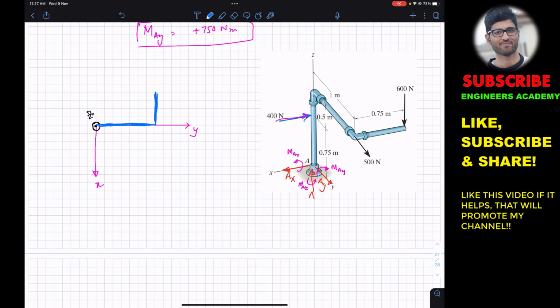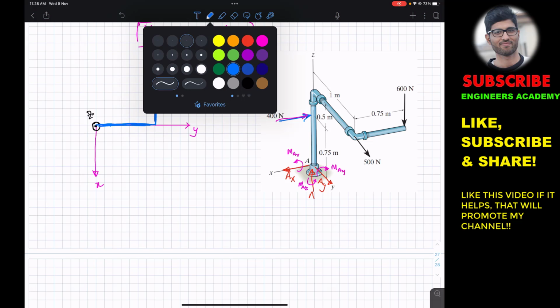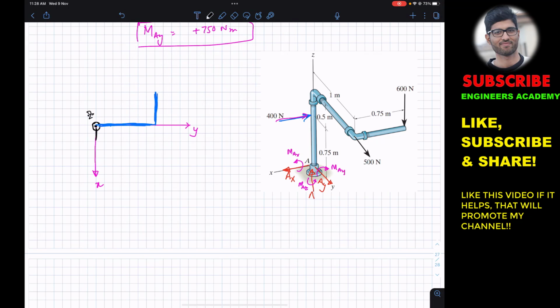And now in this particular diagram, we will be able to see all those forces which are along the x and y, since the z-axis is out of the screen. So now this 400 Newton force is in the negative x. This 400 Newton force is parallel to the x-axis, so we will be able to see this 400 Newton force acting somewhere here.